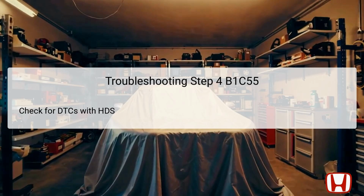In the fourth troubleshooting step for DTC B1C55, you will check for any diagnostic trouble codes using the Honda Diagnostic System, HDS, after the necessary waiting period. This systematic check allows you to see if the DTC B1C55 has reappeared, indicating that the issue is ongoing. If the DTC is still present, this confirms a persistent fault that must be addressed through further diagnostics.